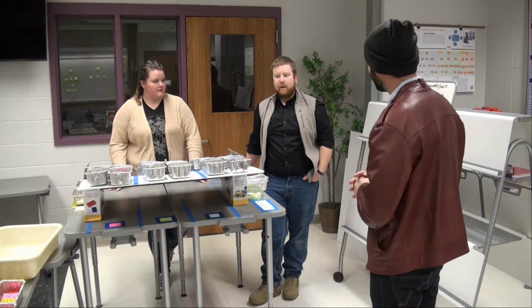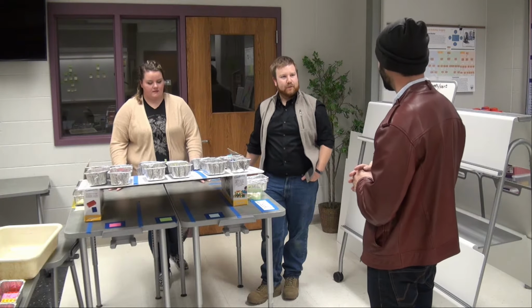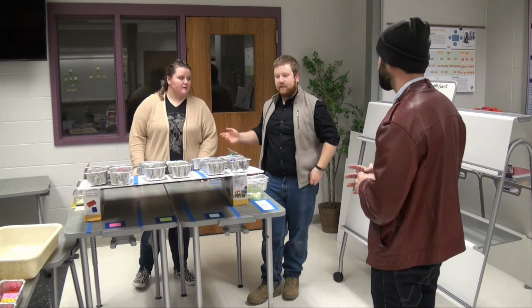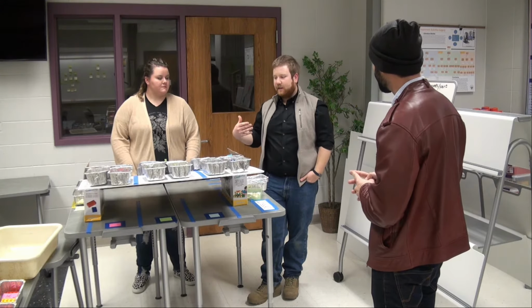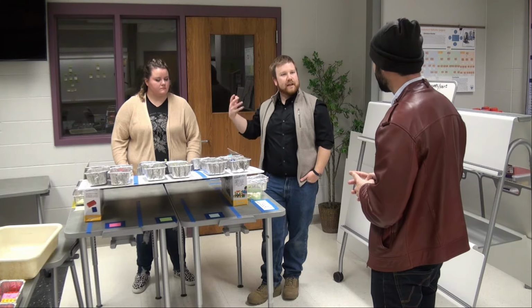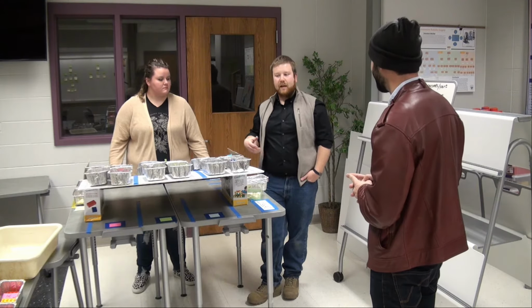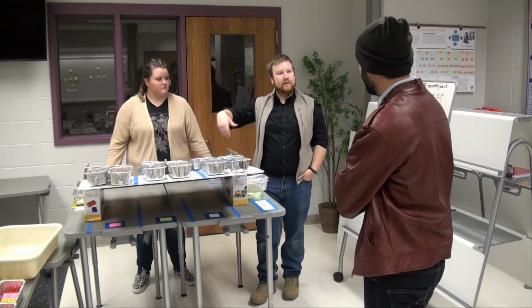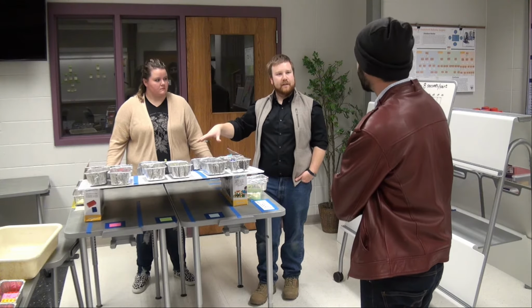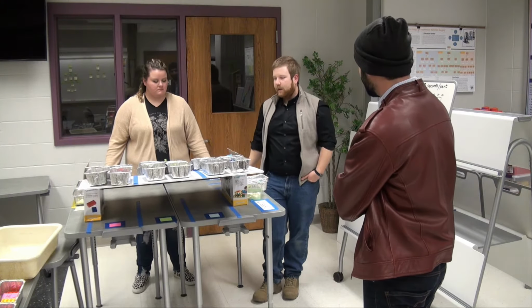Well, if you remember in round 3, it was all about balancing. So you were an assembler along with Sarah, and we did a time study, figured out that Sarah's cycle time was less than the takt time, and so we moved you to the supply side to hopefully overcome the material replenishment issue we were having here in assembly.